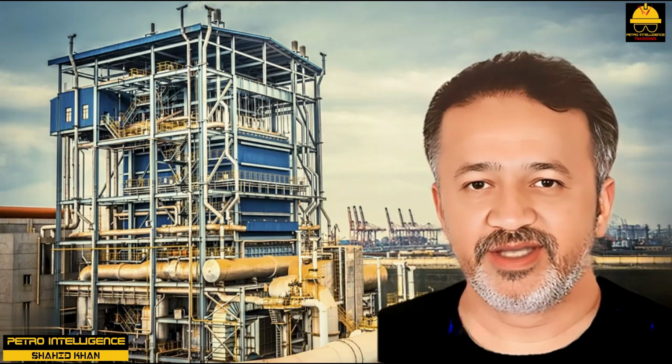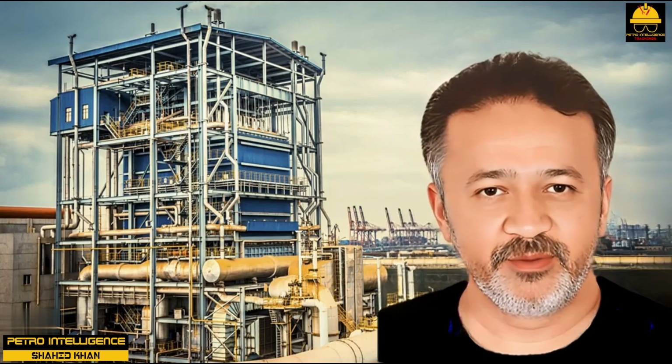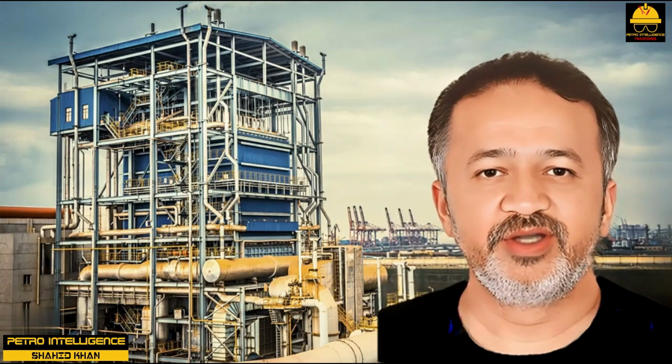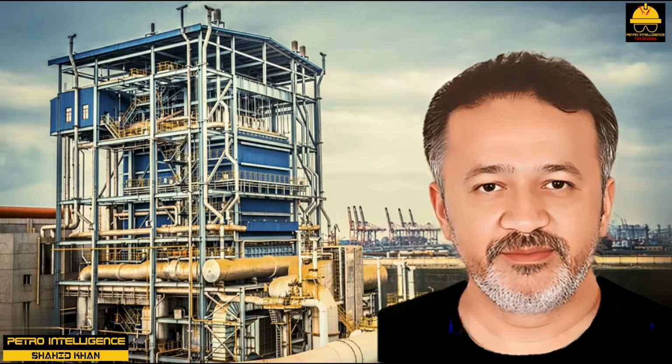In summary, the helical baffle design will not help improve the performance of a shell and tube heat exchanger if the controlling resistance, fouling or film, is on the tube side.